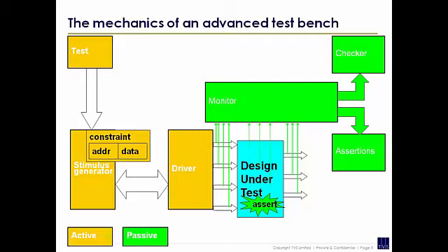So it's the test bench. Yes, there may be a bug in the test bench, and quite often there are bugs in the test bench. I think on ASICs now, there's normally more code in the test bench than there is in the DUT. So by definition, you're probably going to get more bugs in this than you are in this. So there will be bugs in the test bench. You just have to try and fix them.